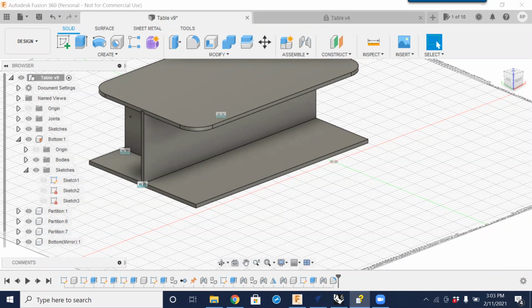Yeah, sure, I'll ask one more. I know you do the cabinet design, you have background in that. With something like Fusion 360, being able to change the material thickness and have that propagate through all these parts, because every sheet of plywood, nothing's 3/4 of an inch, right? It's 0.68, 0.713. Do you find this a really useful tool? So are you doing those designs in 360 now just to take advantage of things like that?